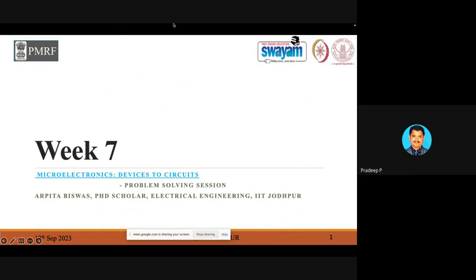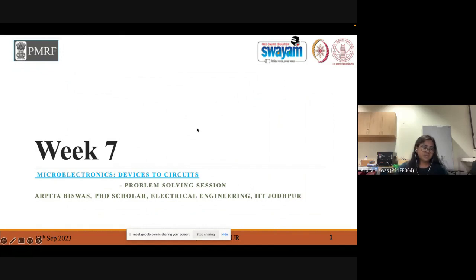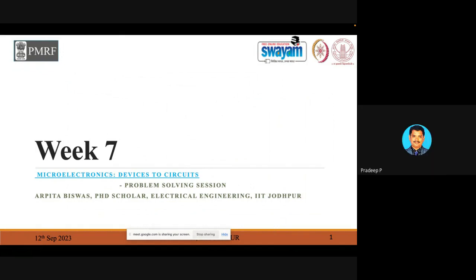Madam, sorry to disturb you, but I will ask one question. If it is possible, you can guide me, madam. For any time constant calculations, is there any fixed procedure, for an RC circuit, an LR circuit, L by R, for different combinations of R and C? Suppose input is applied at R1 in series with C1, and output is taken across the parallel combination of R2. Then the time constant is R1 plus R2 multiplied by C.